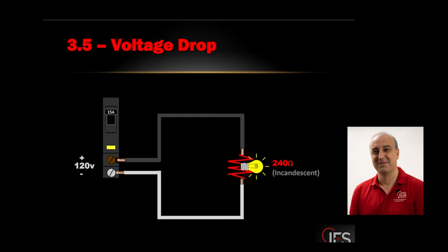No, if you don't have any return path, you won't have a circuit. So if you don't have a neutral, you have another phase conductor, right? It's like a 240 system. Is that what you're thinking? If you only have one hot and nothing coming out, you don't have electricity flowing. Your circuit is not complete. So there's got to be a return path.